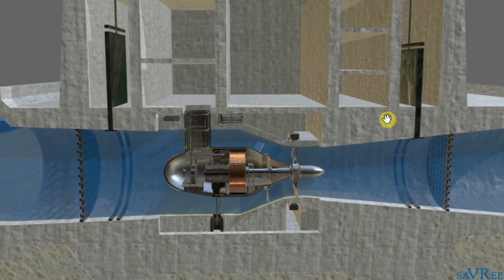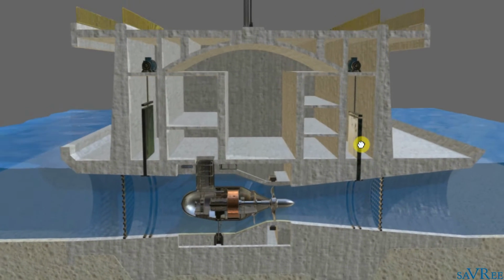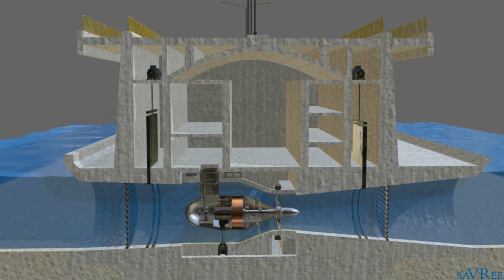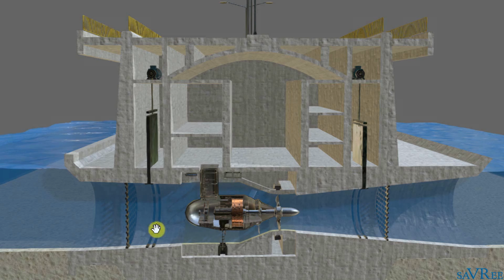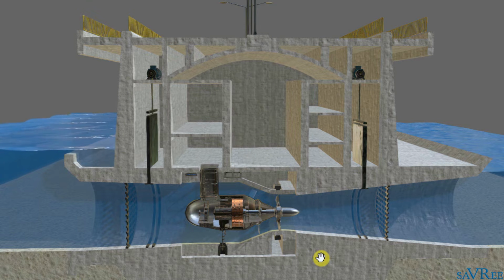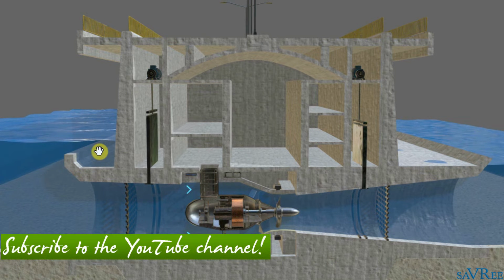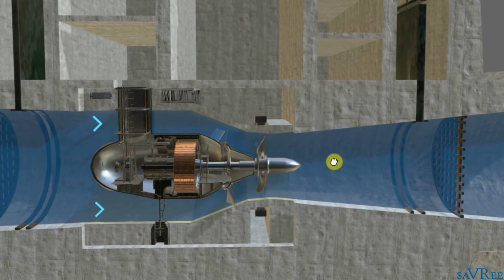Let's talk about how we generate electricity from the movement of water caused by the tides. So I'll play the animation, and we can see already that the water level on the left-hand side of the screen is gradually increasing. It's increasing because the tide is coming in. The reason that the water level is not increasing on the right-hand side is because the wicket gate was closed.